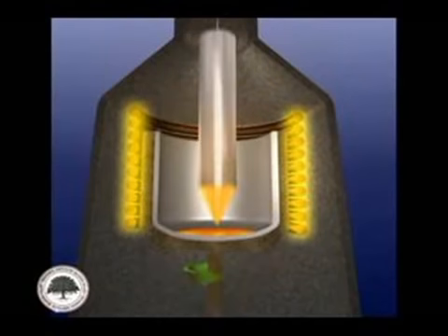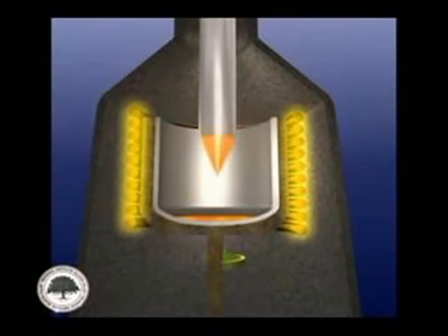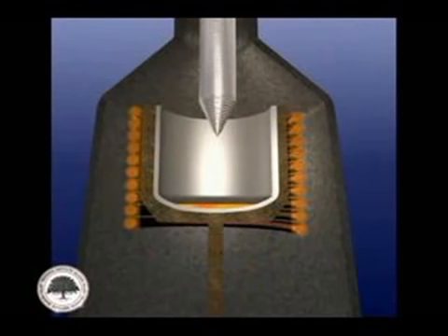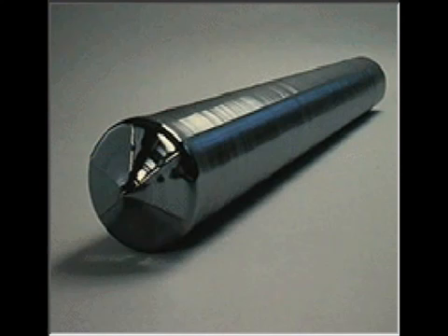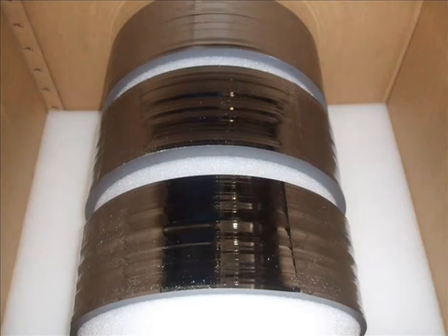of the single crystal. As the seed crystal is slowly raised upward, the molten silicon will solidify in the same structure as the seed. That is why this process is known as growing, which is producing a new rod of single crystal silicon from molten silicon. The large cylindrical crystal silicon is called an ingot or boule, which can be grown to 300 mm to 400 mm in diameter.